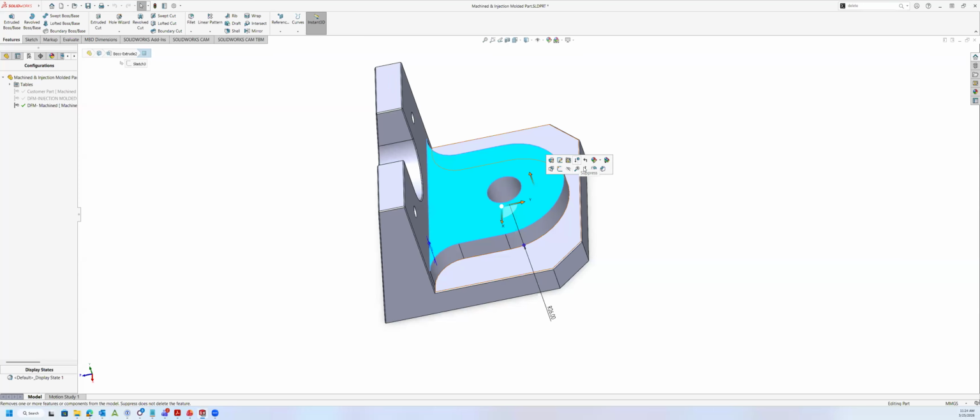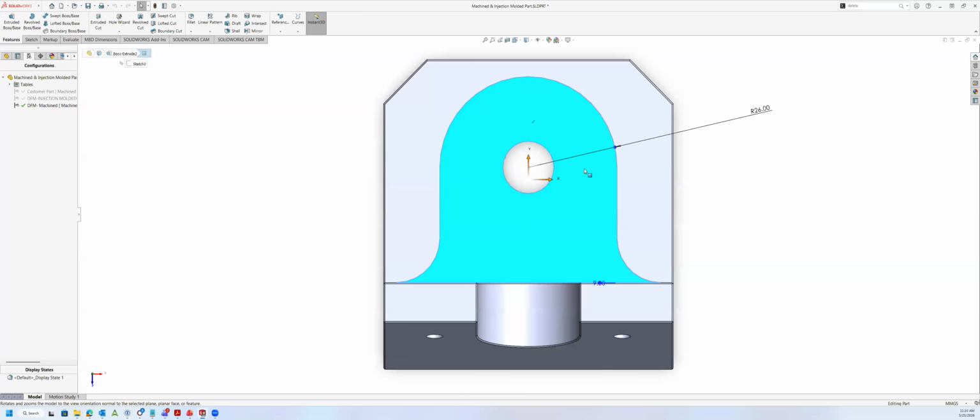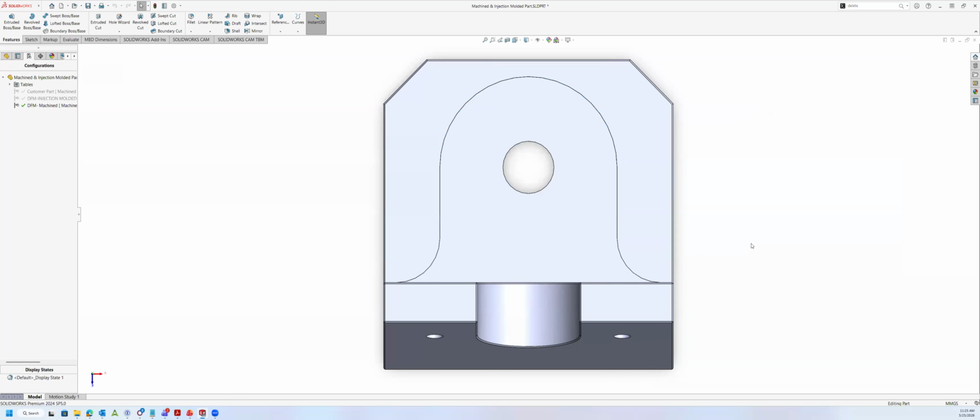When incorporating overall tolerance, you can just do a tolerance stack up of your related machining tolerance, the tolerance of the actual connector, and any necessary tolerances required from the customer. On this part, it's more of a loose fit. He's not requesting precise mounting locations and everything else, so we would just use standard tolerances when machining this.